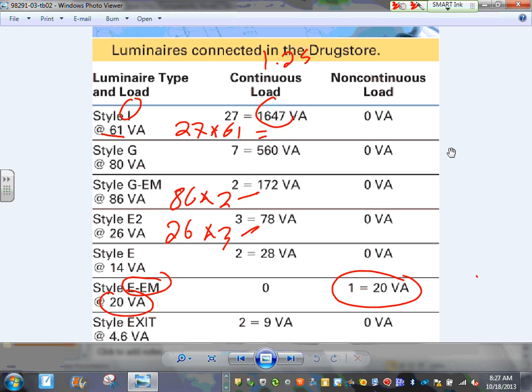Do you know why we don't count the emergency light? Because they're not normally on. They're on when the system is down. So they don't contribute to the load on your system unless you're using a fixture that works dual duty, emergency and normal lighting, which they do. These bug eyes, for example, Derek, don't take a whole lot, like 30 watt. But do we count them? No. Why? Because they're only on when the system is down. So they're not going to add anything to your feeders. Not a whole lot of load to your feeder. Adam, they are the same value.